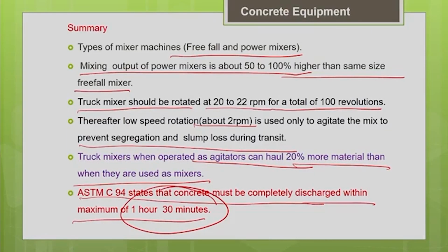Okay. So, accordingly only you have to make the choice of whether to go for the ready mix concrete or not. So, depending upon the distance between your job site location and the RMC batching plant, we have to plan whether it is possible to deliver the concrete within this particular time duration. Okay. Accordingly, you have to make a decision.